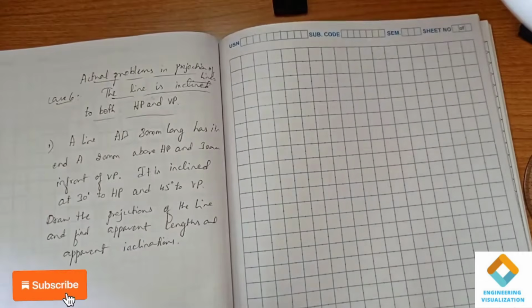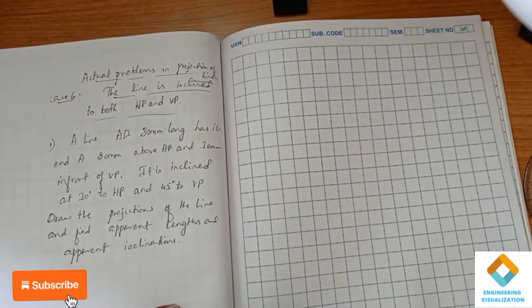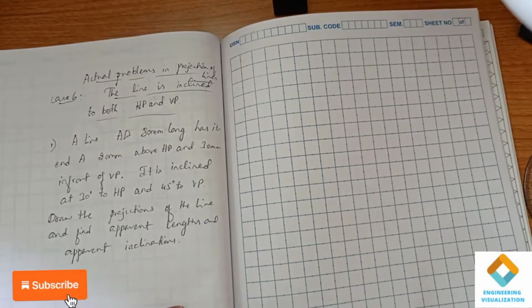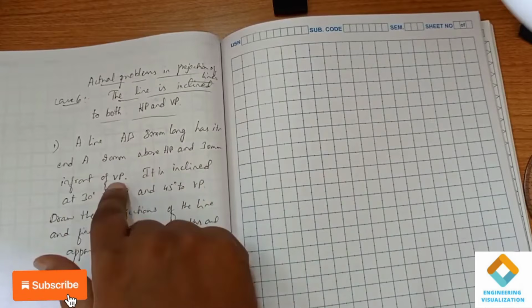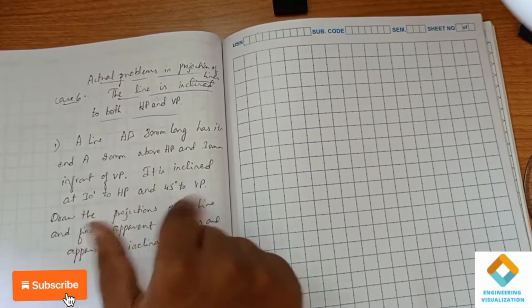This case 6 is where the line is inclined to both HP and VP. The line inclined to both HP and VP is the actual problem in projection of lines. So now we are dealing with the actual problem. You can see here the line AB, 80 mm long, has its end A 20 mm above HP and 30 mm in front of VP. It is inclined at 30 degrees to HP and 45 degrees to VP.